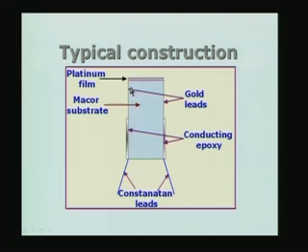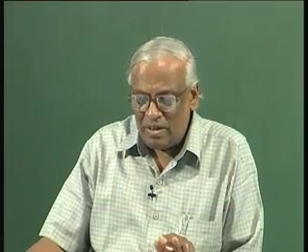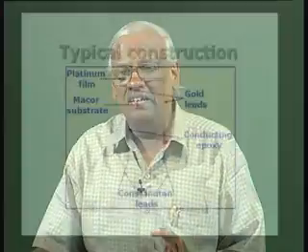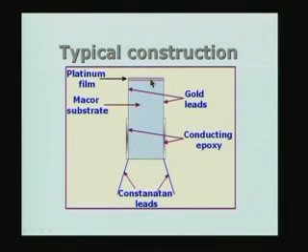Therefore, essentially this is a resistance thermometer, the film itself acting as a resistance thermometer, and the temperature of the surface when it is exposed to a heat flux is measured by following the resistance. And you know already that the resistance increases with temperature more or less linearly, and if we do not allow the temperature to swing by very large values, the linear assumption may be justified.